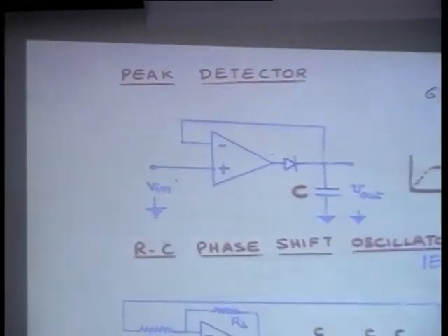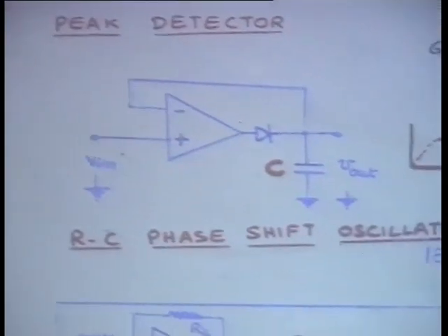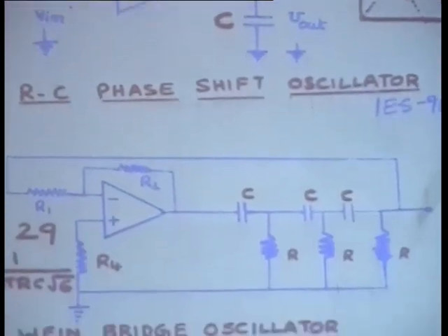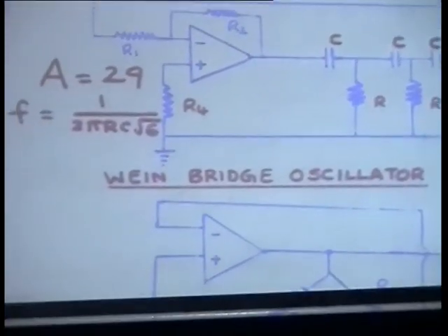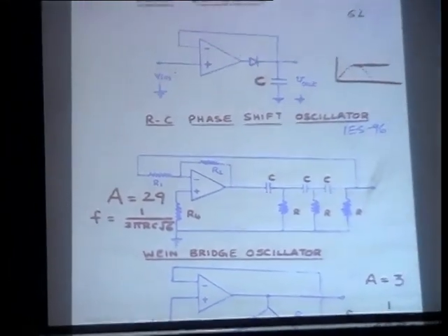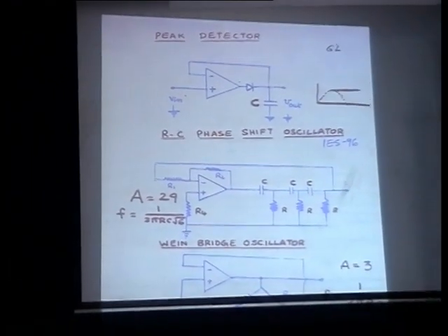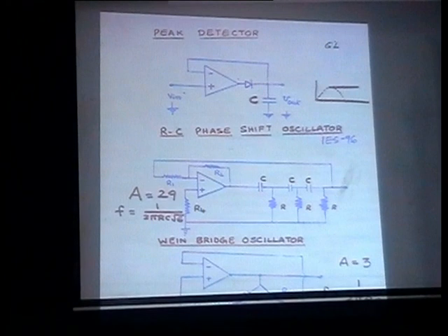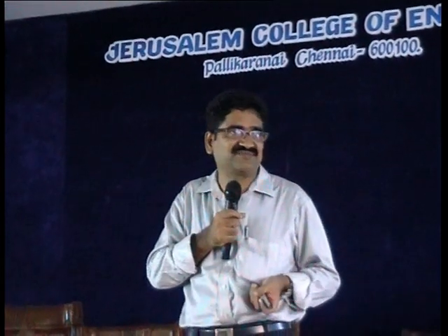So whatever you see in electronics is a repetition of what you have already studied. For example, low pass filter, you have already studied RC circuit, one op-amp is added. Is it not? Integrator, you have already studied RC circuit, one op-amp is added. So that I get all the benefits of op-amp: high input resistance, high gain, low output resistance. Those benefits I will be getting.